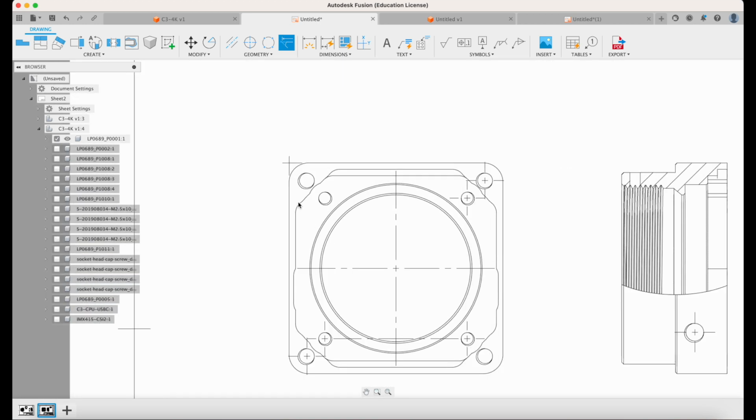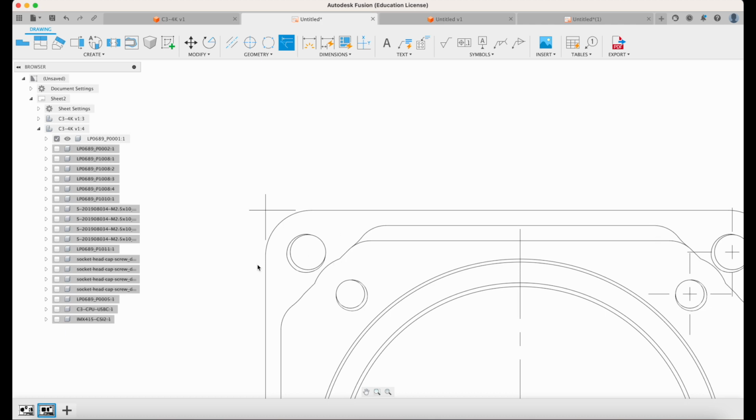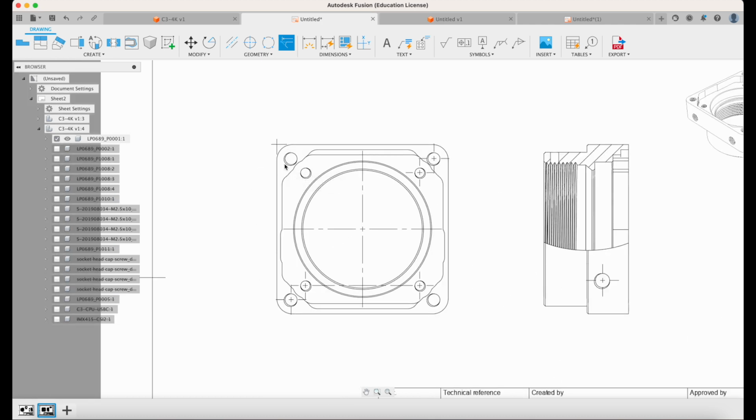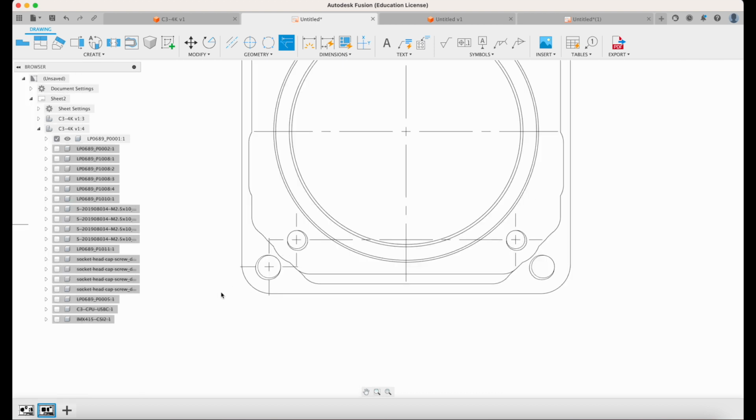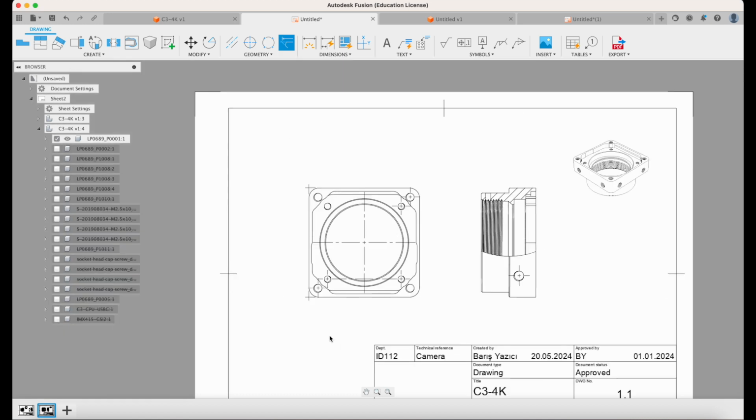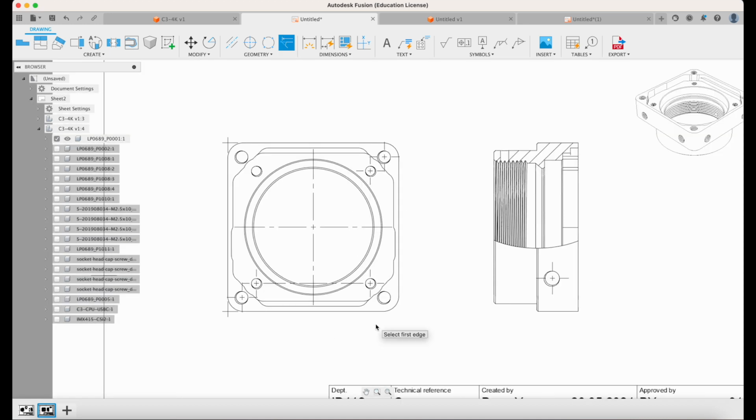Okay, as you can see, because it would be hard to measure a fillet, by creating an extended edge, I'll have a much easier time measuring from corner to corner. Let's do one for the bottom as well. Select that one. Select this one, so I have an edge extension. Now, we're getting into dimensioning.